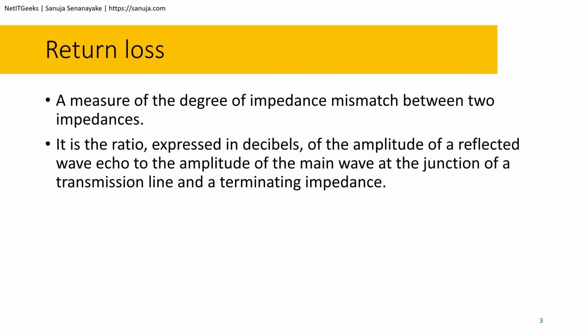So the first definition I will cover is the return loss. A return loss is a measure of the degree of impedance mismatch between two impedances. It is the ratio expressed in decibels of the amplitude of a reflected wave echo to the amplitude of the main wave at the junction of a transmission line and a terminating impedance.